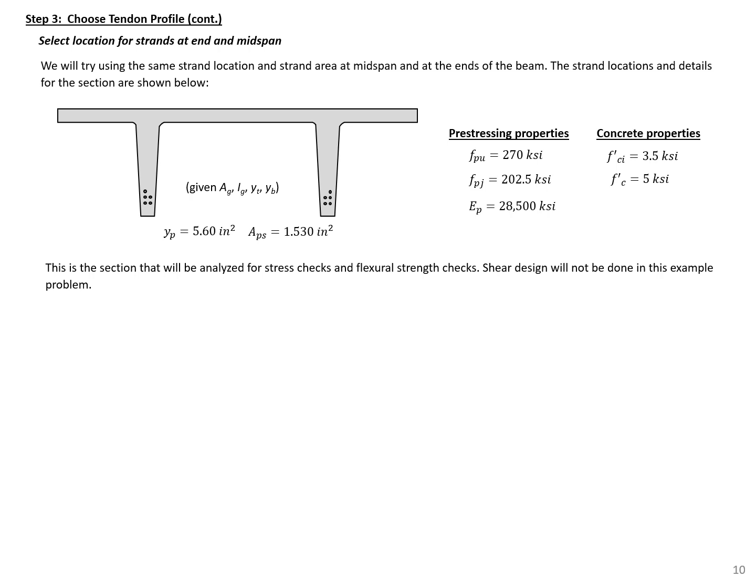At this point, we're transitioning from the design process to the analysis process. So typically what I want you to do and what I'll do is I'll draw the actual section that we'll be analyzing. So here's our section with the centroid of our strands, the total area of our strands, and the material properties that will start off our analysis when we're checking our different design limits.